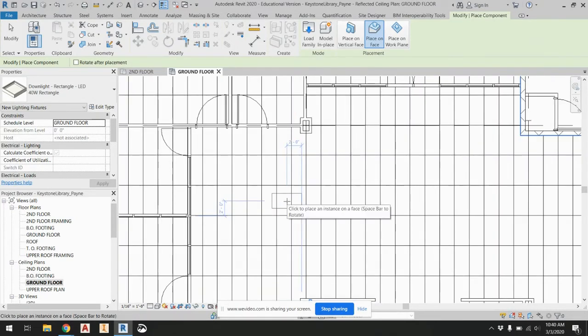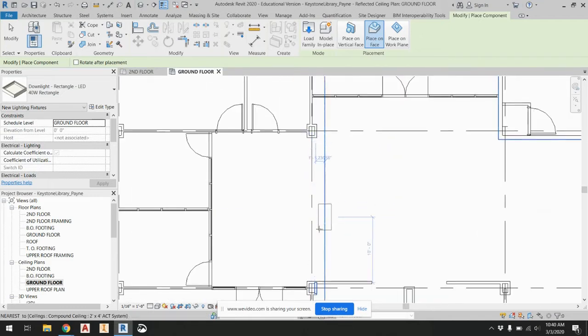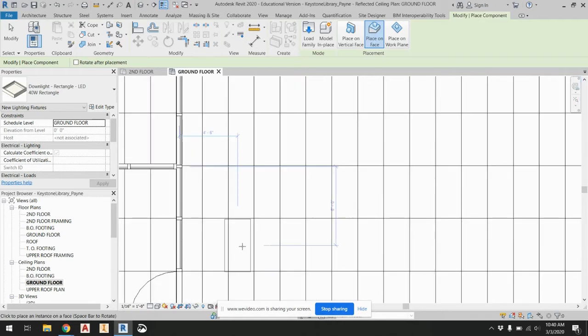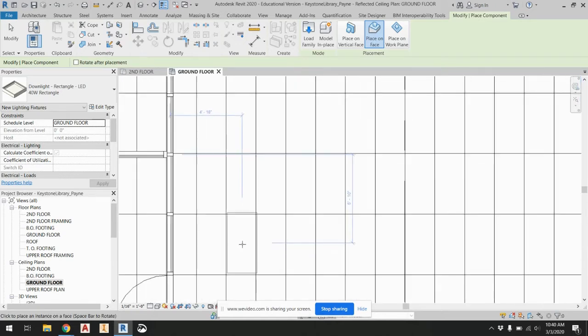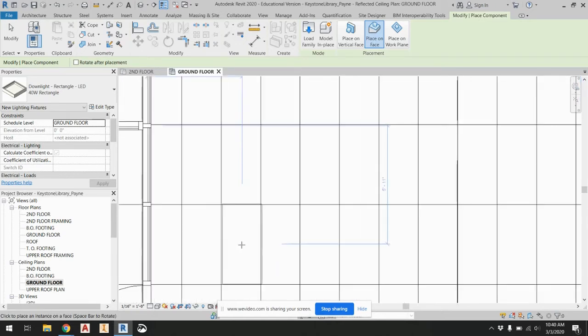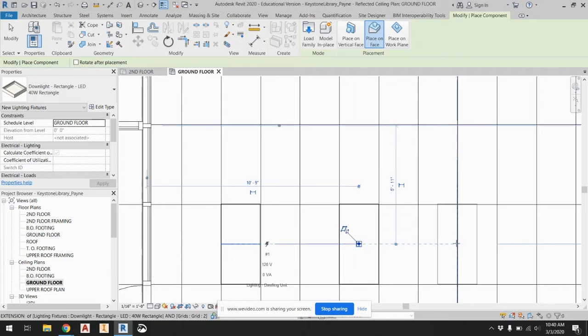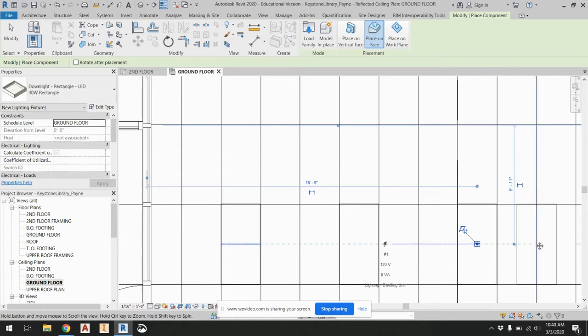All right, so compared to the direction of my ceiling tiles right now, it's turned sideways. So if I hit spacebar, now you want to just kind of place them. And again, it's kind of up to you how you place them. I'm going to try to place them inside of where the tile is. All right, and I'll maybe space them out every other tile like this. Or sorry, every 2 tiles, or every 3rd tile, I should say.